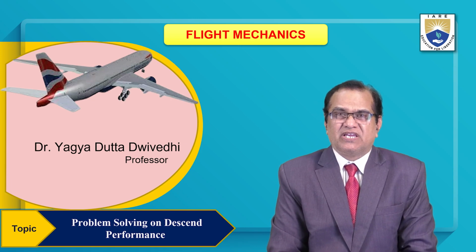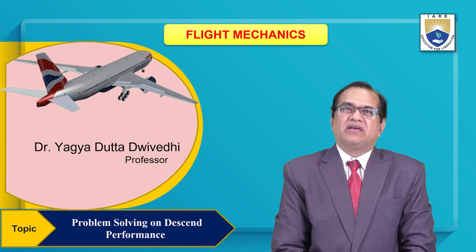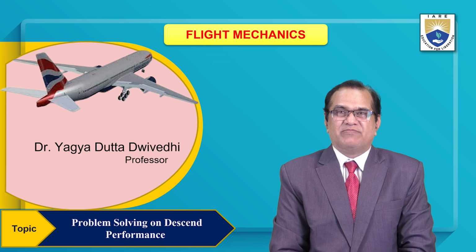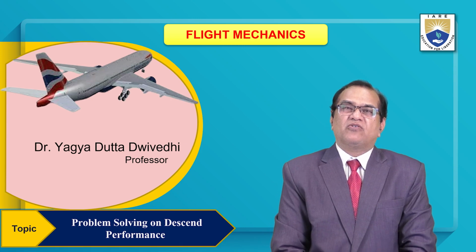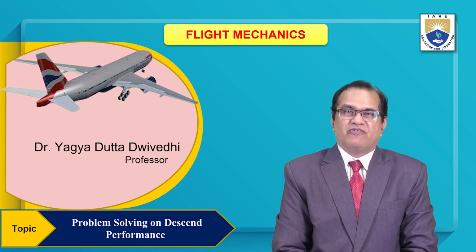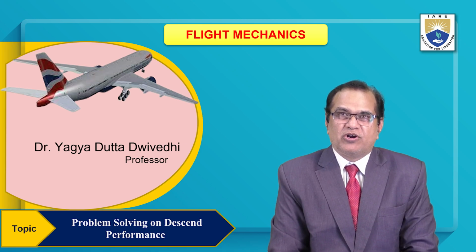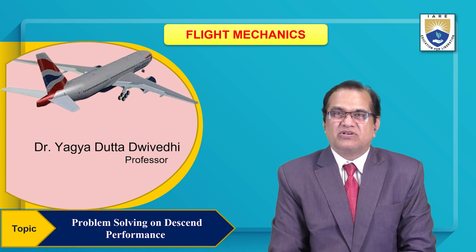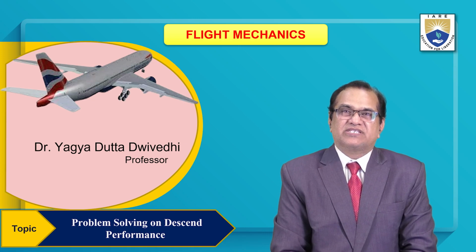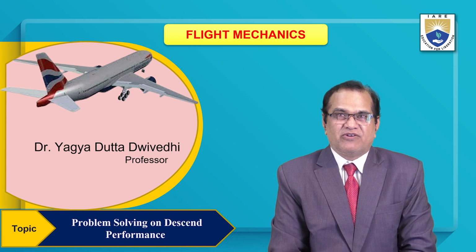In Module 3, we have discussed climbing performance, best climb angle, best velocity for the climb, minimum velocity. Then in Module 4, we have discussed maneuvering flight, which covers the load factor, pull up, pull down, VN diagram, safety margin for the aerodynamic zone and the structural zone, VNE, that is never exceed speed, VM, that is maneuvering velocity, maneuvering point, and so on.